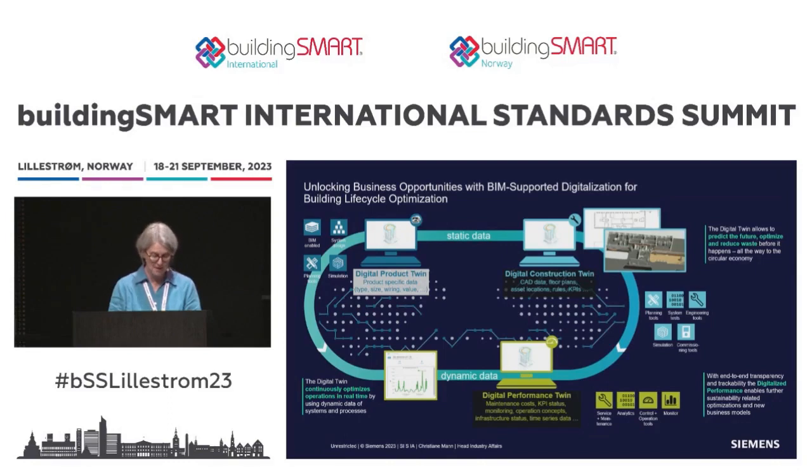BIM objects are digital representations of physical products that also contain other important data, such as product information, installation instructions, energy consumption, eco-labels, operating cost, or product lifetime. Merging the virtual model of a building, which is the construction twin, with the BIM objects that provide live sensor data, the product twin, creates the performance twin of your built asset. And the insights gained with a performance twin form the basis for sustainable operations.